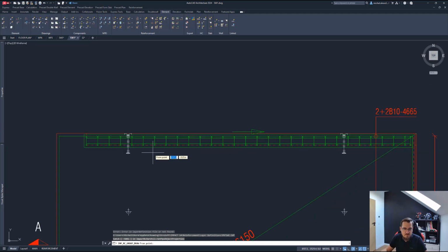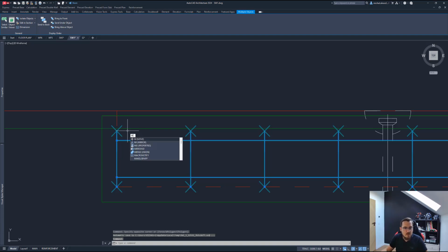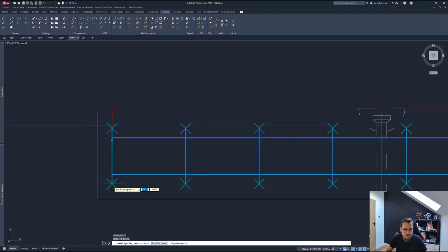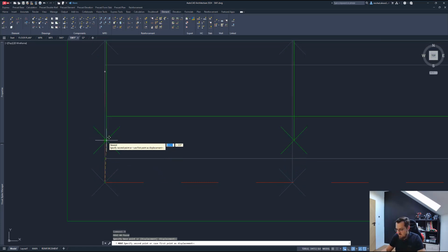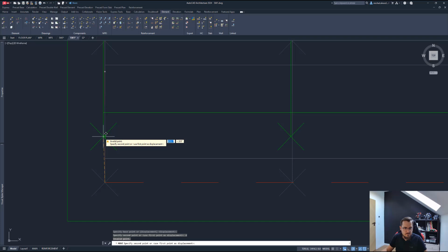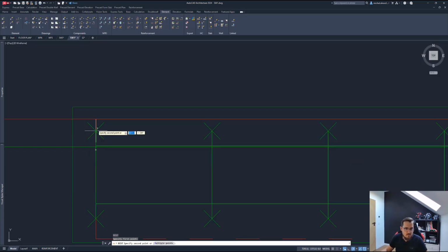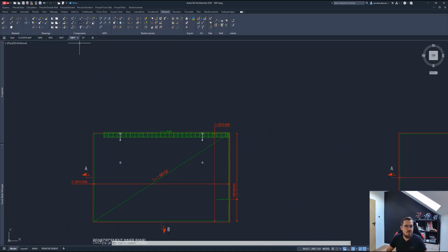And as you can see, I now have that group placed, but it's slightly off. I still need to move that. So let's move that vertically. It's not exactly on the line. Let's move that by 25. Let's go displacement. Let's go 25. Okay. That's going to be delta Z 25. Okay, should be sufficient for the demonstration. It should be perfect. And let's refresh the drawing now.